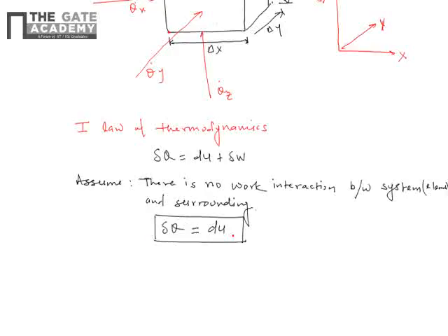And since all the heat transfer takes place at constant pressure, we can say the change in internal energy is nothing but the change in energy content of the element, which is given as m Cp delta T. Since rho is the density of the element and its volume is delta x delta y delta z, mass can be written as rho times del x del y del z.